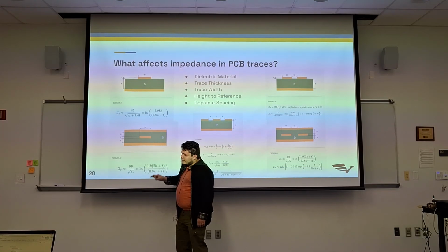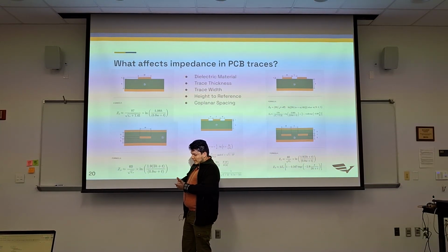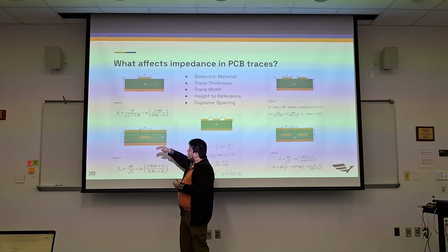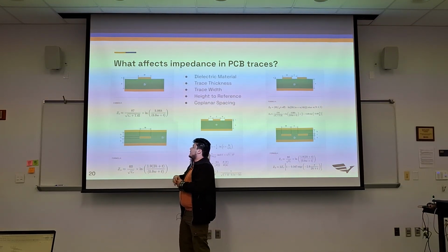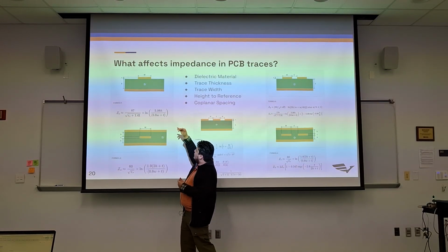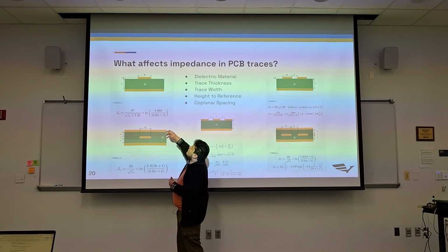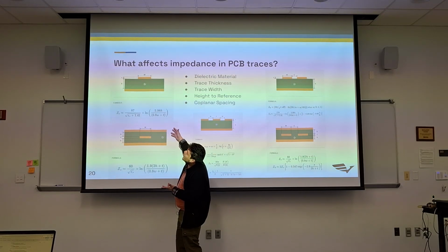And then if you really want the absolute best quality and smallest trace for controlled impedances, you could do this. This is something you would see a lot more in 6-layer boards, or I mean, 6-layer is a little strange, probably closer to an 8-layer board.